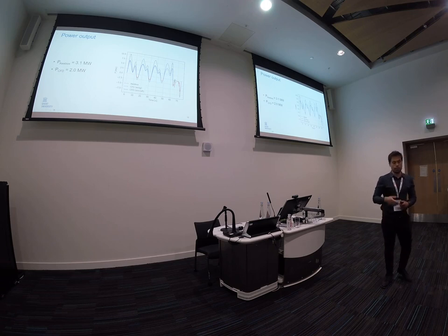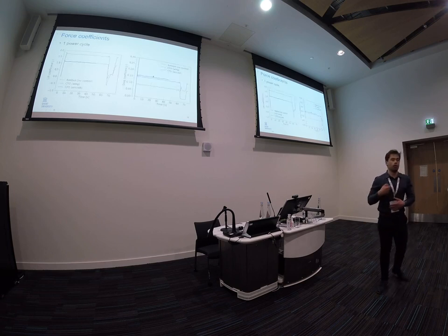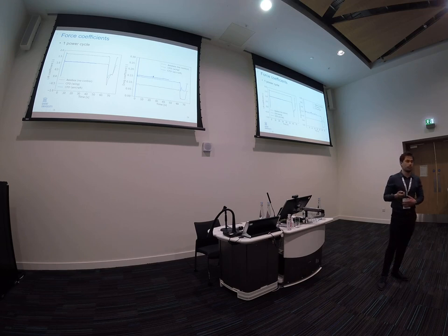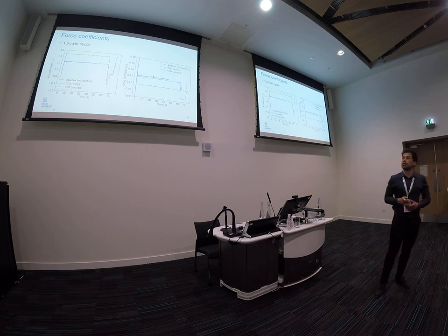the prediction using the CFD aerodynamic forces, and this is because when we look at the force coefficients of the CFD model, we predict less lift and more drag. So I plotted here the lift coefficients and drag coefficients of, again, the AWEbox model and CFD, both wing and aircraft. And you see that the CFD model predicts less lift, less performance of the aircraft.